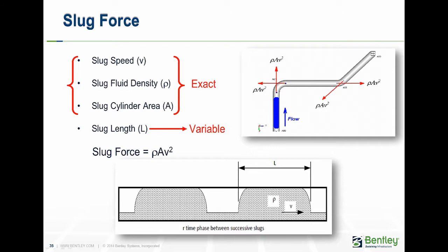Newton's second law tells us that we need a force to produce a change, and that it will be proportional to the rate of change of momentum. By Newton's third law, we also know that the fluid will exert an equal and opposite force on a solid boundary, producing a change of velocity. We also know that the momentum of a particle is the product of the mass times the speed. In a pipe, the mass flow is given by density ρ times area times velocity.